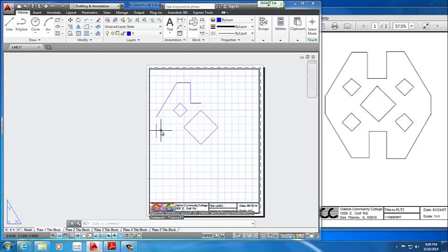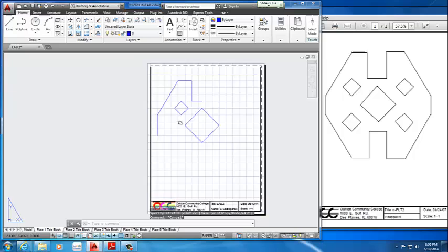And I'll stretch this line. So you have 2 options, stretching or moving. Moving is that you have to use a move command, but to stretch a line, you just select a blue point and you can stretch it from there. Unless you select the center, that's a whole different story. It just moves it. But each end point of a line allows you to stretch it out, so make it longer or shorter, up to you.